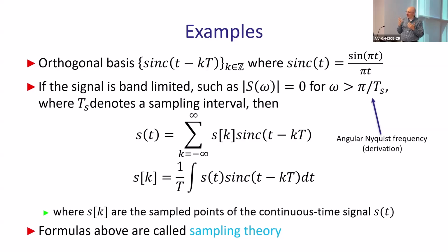So intuitively, to destroy the perfect picture where you can completely reconstruct the entire signal, you actually need very high frequencies between the points to make all kinds of zigzags, and not just connect them smoothly with a particular function. This is why you need a broader band, more frequencies in the signal. And then you will have more trouble reconstructing the signal if it is not band limited, because it can jump however you want between the points and you don't know how, so obviously you cannot reconstruct it. You'll have exactly the same points, but between the points could be anything.